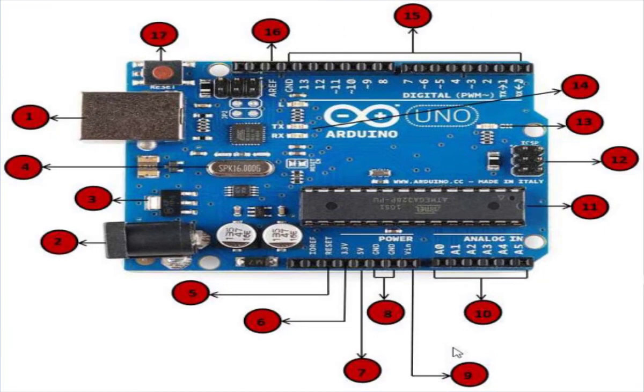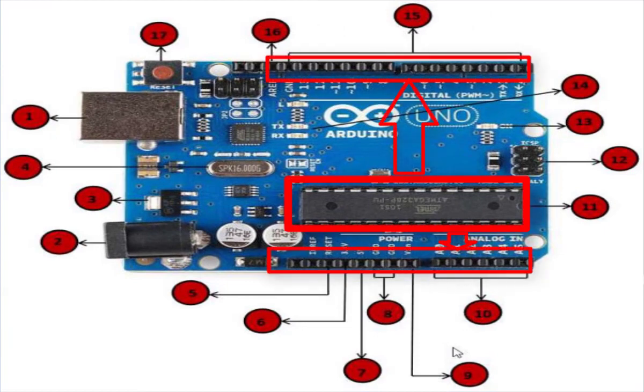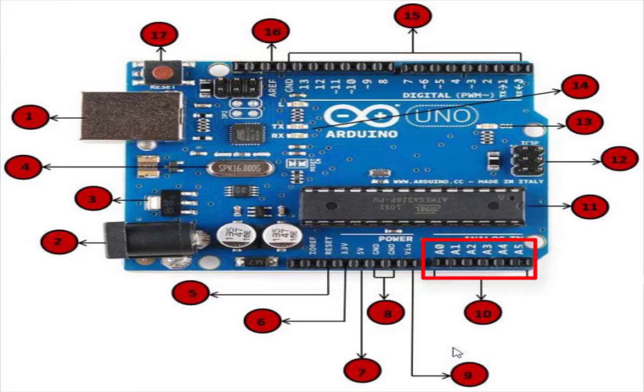The Arduino layout. You can directly access all the microcontroller interfaces from the header sockets. The bottom set of sockets contain the analog input interfaces and access to the voltage and ground pins on the microcontroller. The top header socket contains the digital I/O interfaces. The standard layout of the header sockets allows developers to easily build plug-in devices that interface with the Arduino.